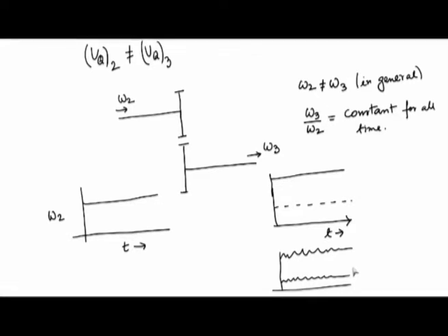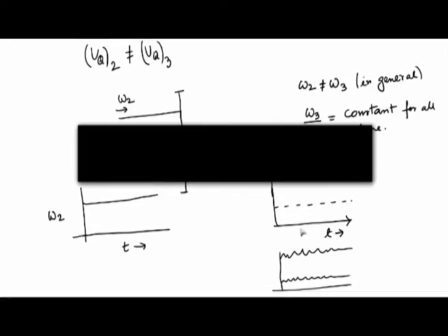Similarly, in the automotive example, you do not want the output of the transmission, which basically becomes the input of the gear of your wheels, to fluctuate. If the input of the wheels starts fluctuating in terms of speed, then the drive quality of your vehicle will be severely compromised. So definitely you wish to get a constant angular speed at all times. The effect of transmission should only be to increase or decrease the input speed by a fixed amount. It should not be changing with time, and this we will realize is a very severe requirement actually.